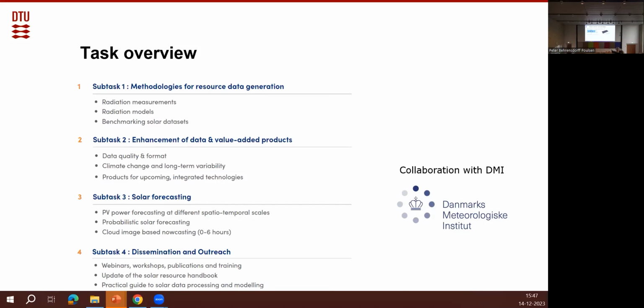But first off, let's take a look at the kinds of solar irradiance data. We can typically have them come from 3 different sources. They can come from measurements, so expensive. We can have them come from satellite estimated models, so they have good coverage, are decently accurate and quite cheap. And then they can come from weather models, which are somewhat inaccurate, but often have global coverage and are free to use. But first of all, satellite irradiance data is typically what we would choose to do a feasibility study of a project, and essentially used in all.